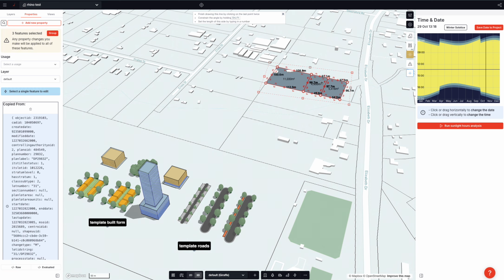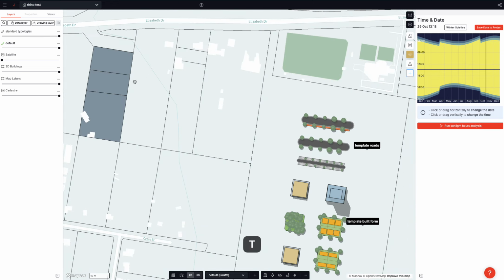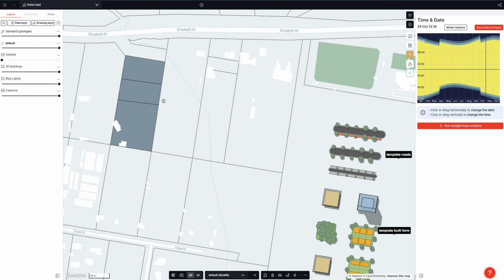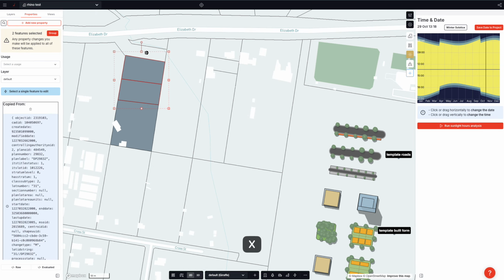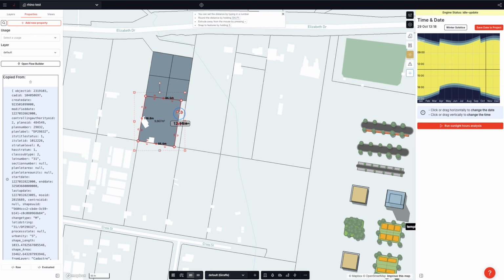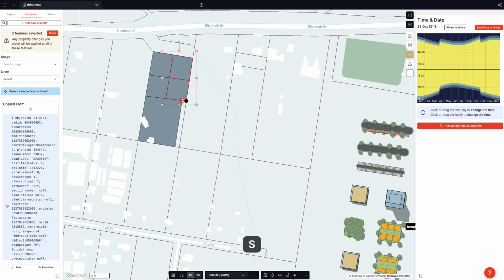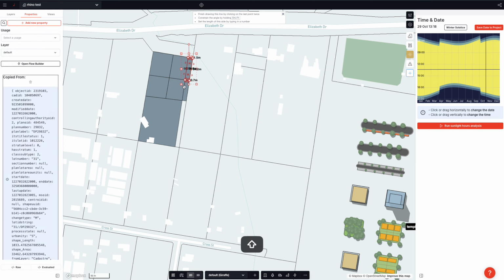And what I'm going to do is put some mixed use and commercial to the north and some residential to the south. And so I can do this, and I'm doing this extremely explicitly. There's no magic here. And I can pull this back 10 meters because me and the neighbor are going to share a 20-meter road reserve, or I can use the X key and slice it like this.